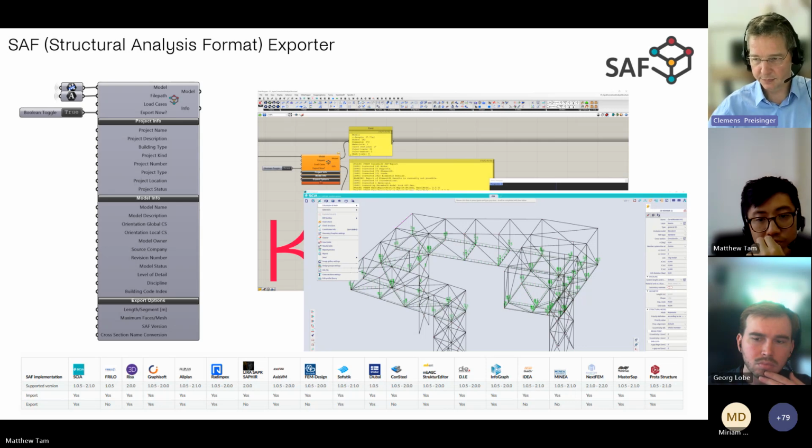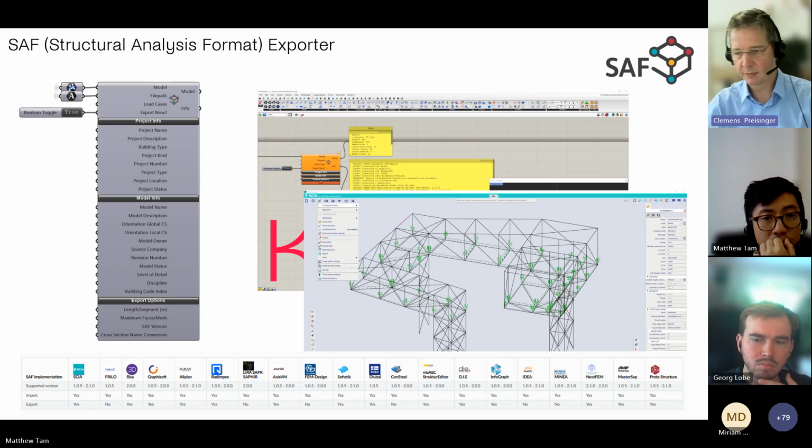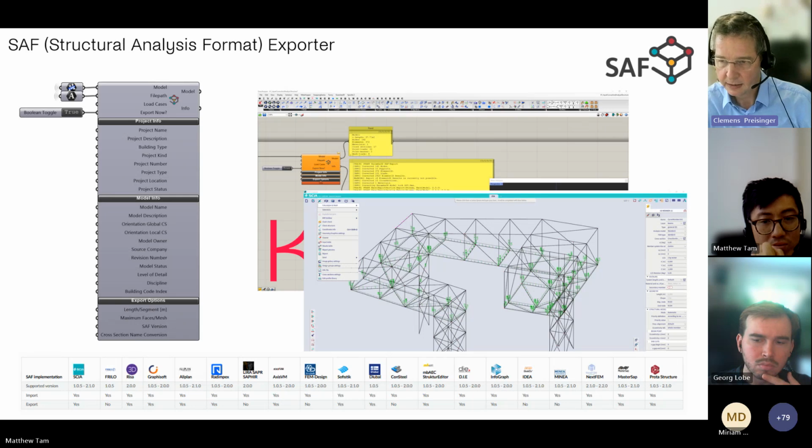And since Karamba is based on a linear elastic material, mainly at the moment, pre-stressing doesn't change the stiffness as it would in reality for reinforced concrete, for example, because you avoid cracking. But for cables, for example, it makes sense to pre-stress them. I hope this answered the questions.